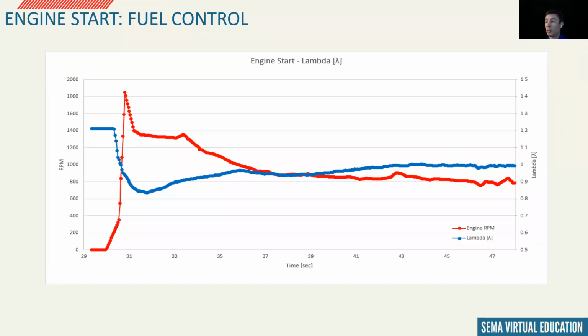Like mentioned before, we will not have the help of closed loop fuel control for about 7 to 10 seconds after the engine start. You can see where the closed loop fuel control engages around 10 seconds into the test. During this time, it looks like we had a 3 to 5% error. We want to keep this error as small as possible.